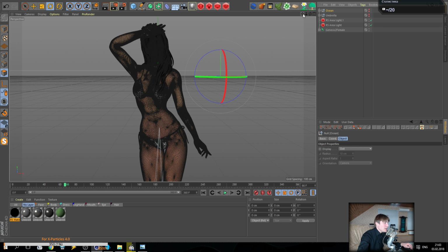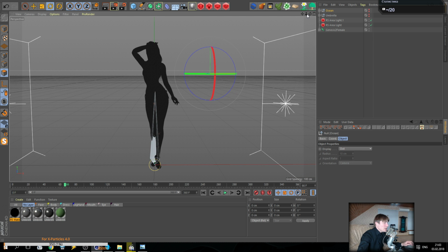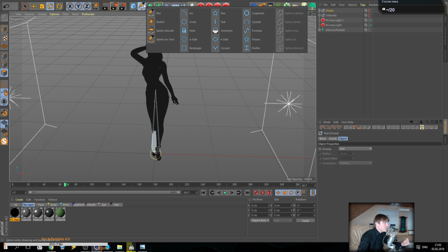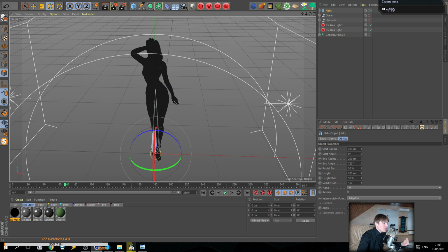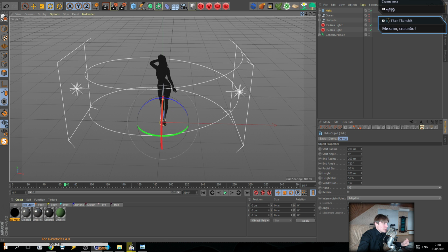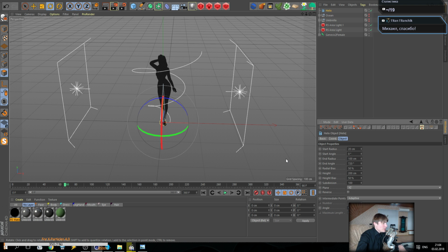So I am going back to create a water simulation. So it will be for everybody who likes to see ocean, who likes to see water simulation. So going to spline and create a helix, change rotation like this, and downstairs make a minimum, upstairs make it maybe 100, yes, maybe 100.